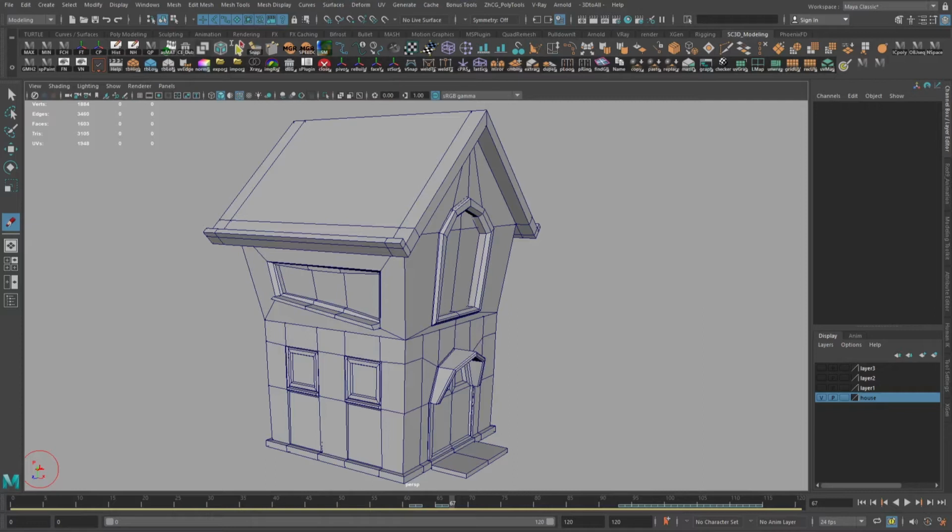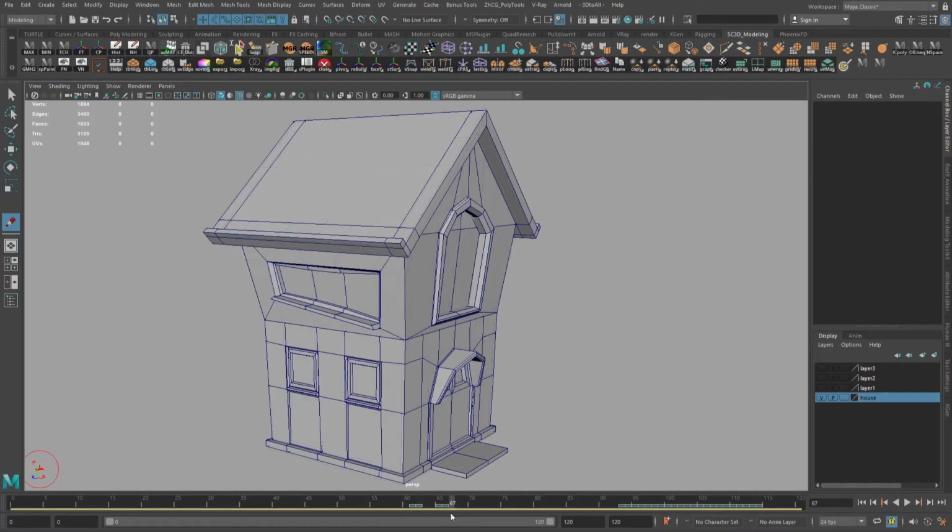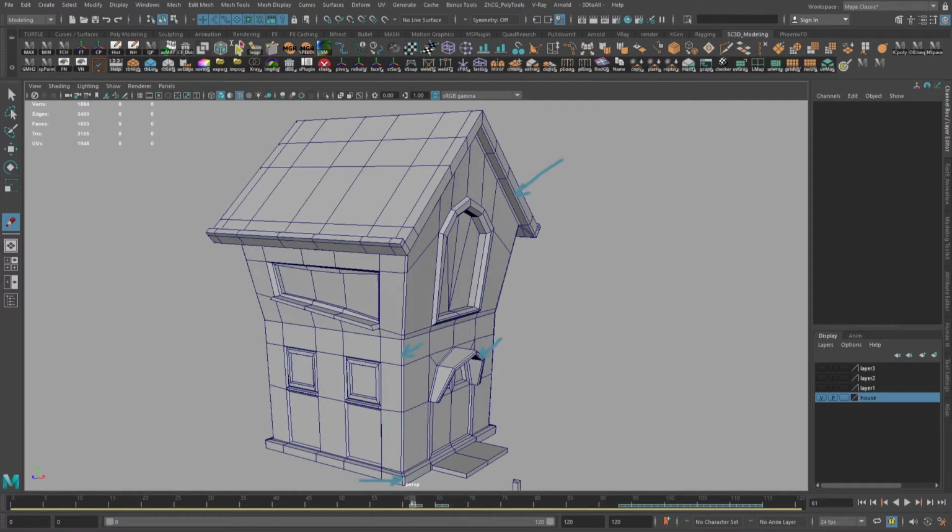After that, depending on your project needs, you can merge or group or just leave separate objects. I've decided to merge it into one object because of the project goals. Because of that, I was playing a bit with topology, as you can see. Great, so the house is looking better and better. When you decide that your object is completed or near completion, do not forget to check hard edges, which will be in the focus of view. Bevel in order to get a more pleasant view.